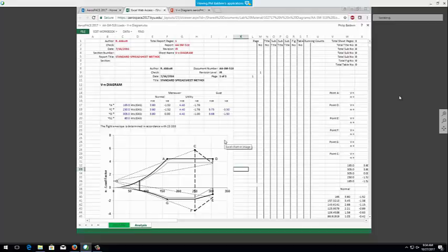But I can take that and paste this enormous equation, and if I look at it here, it's just a big equation that I linked to a bunch of parameters, and I can go through and change those and then see what the resulting power loading would be. Now, rather than do that, I instead integrated it into a constraint sizing spreadsheet. So this is similar to what we had before with the constraint sizing spreadsheet. I got rid of the variables that I didn't account for. I didn't account for the density, which matters mostly in terms of thrust, and I could have improved the model in that way, but I didn't.